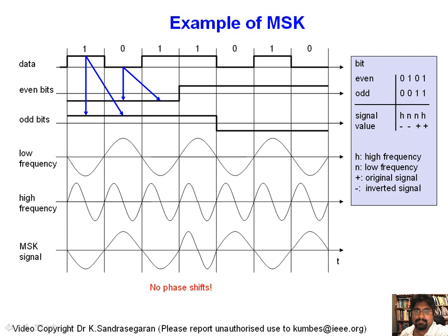And then there is a frequency associated with the even bits. So we have two particular frequencies. If the even bit is 0 and the odd bit is 0, then we transmit a carrier of high frequency. So for example, here we have the even bit is a low, a 0, and the odd bit is a 1. So a 0 and a 1 will produce the lower frequency. So the low frequency is transmitted between those 2 points, and so forth. So you can work through this table.